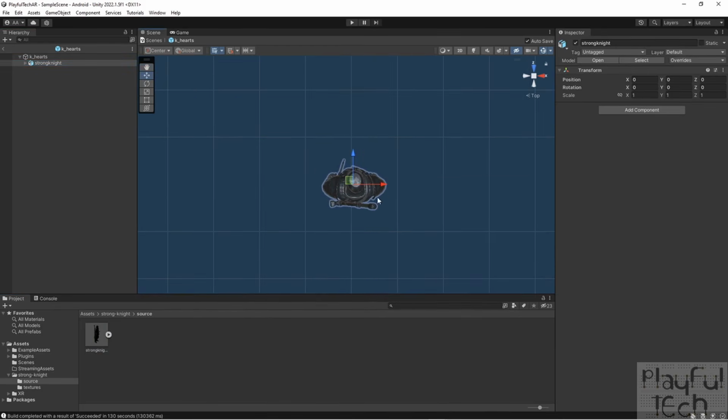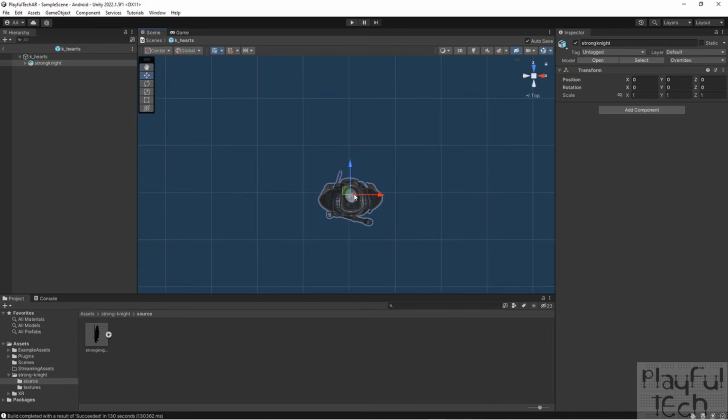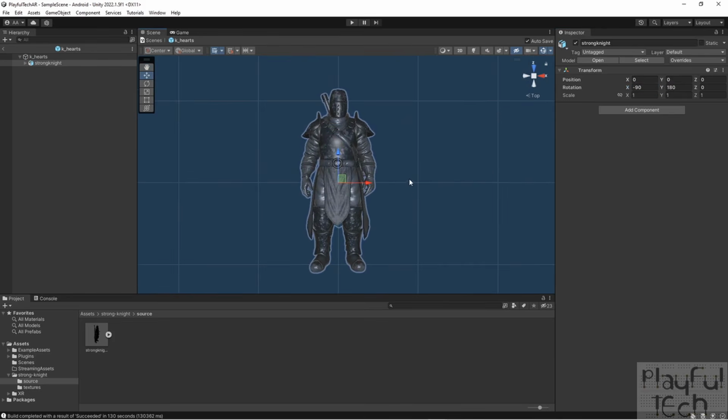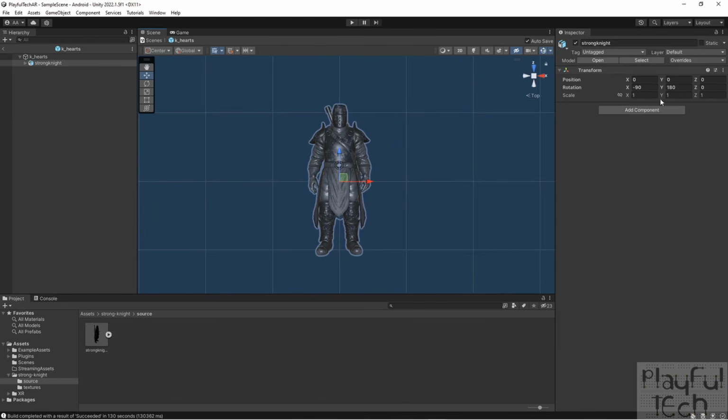Now, the way that the orientation of the axes works, what you need to do is position your 3D models so that they look correct when viewed from the top. So it's sort of the Y and the Z axis are flipped over slightly. So to just tilt this guy round, I'm going to spin him 180 degrees on the Y axis first, and then lean him back 90 degrees there. And just as with my cube, I'm going to want to scale him to the appropriate height. So let's make him 15 centimeters high in all dimensions there.